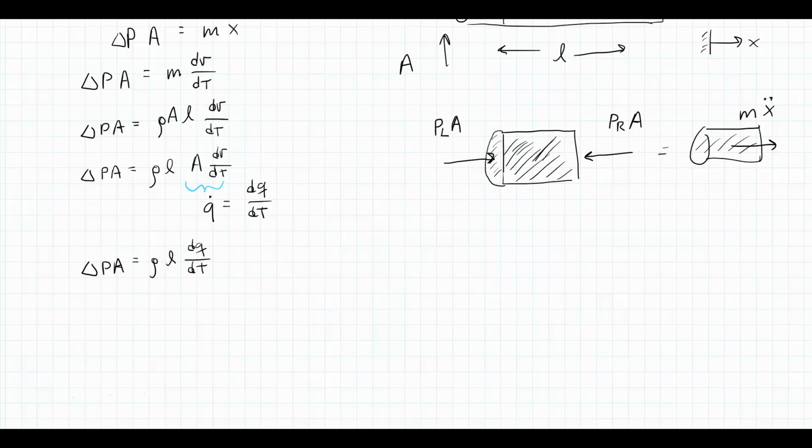So now, where are we getting? Well, we have a P in the equation, we have a Q in the equation. Again, what we're looking for in these elements is the relationship similar to what we saw in the electrical systems between the voltage and then some impedance and our current. We're going to have a pressure and then the equivalent impedance, and then our current is going to be our volumetric flow rate, our Q. So this is the form we are trying to get into.